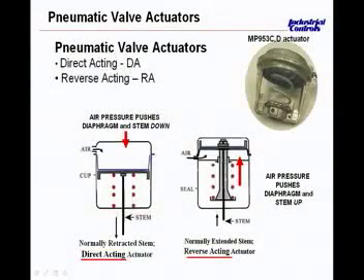Also in this picture here, it's maybe a little bit easier to see in the upper right-hand corner, the fitting that's attached to this particular actuator is above this round top, and therefore the air is being introduced into the top above the bladder. If there are some other ones that might be designed, it might come underneath here and then bring in the air pressure around or underneath the bladder. So just things to look for.